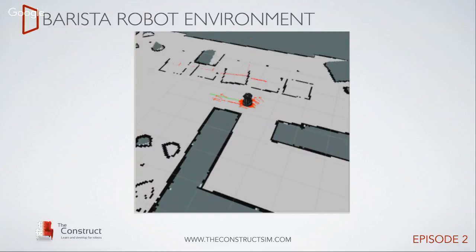The next thing we did was test the navigation. We started the ROS navigation stack with the Turtlebot. It's quite easy. If you follow the tutorials in ROS, you can find it. If you do it through the Robot Ignite Academy, it's even easier because it's step by step, with many indications and practical examples. We were making the robot navigate using the ROS navigation in the simulation.